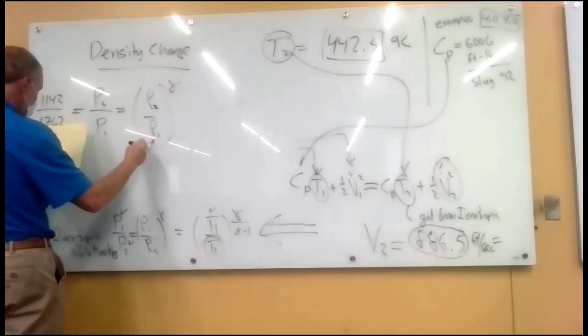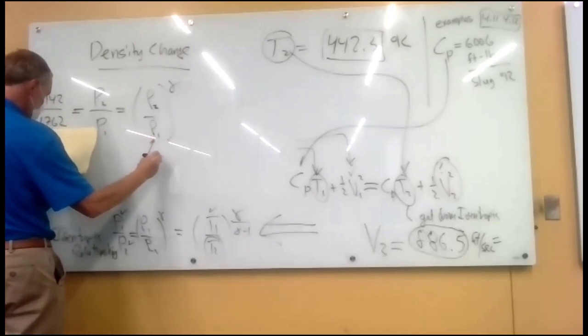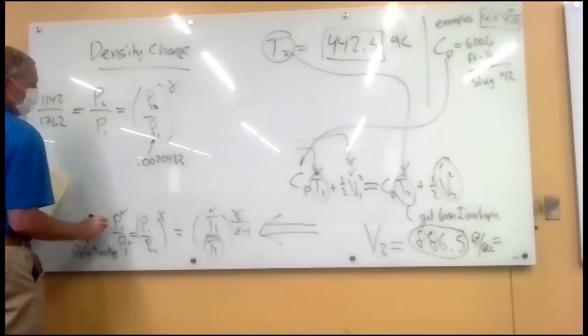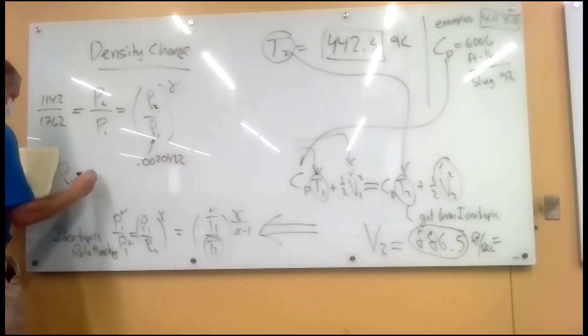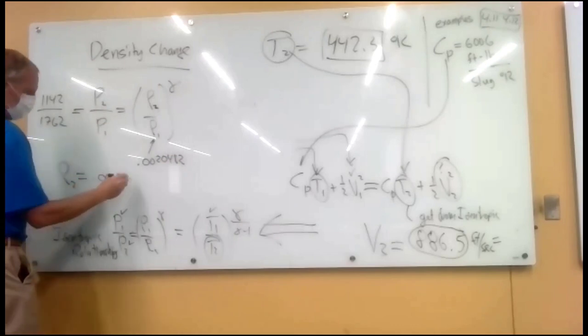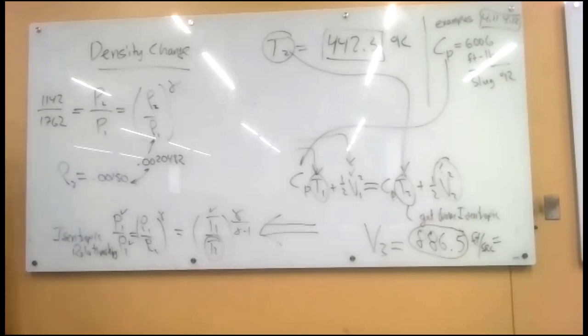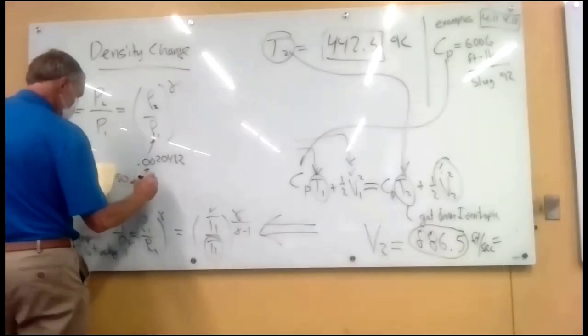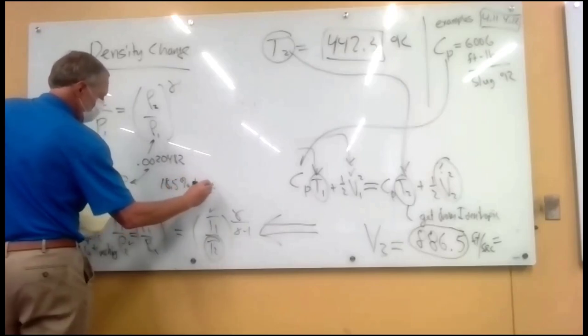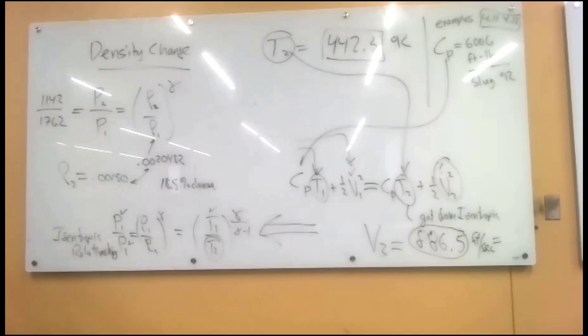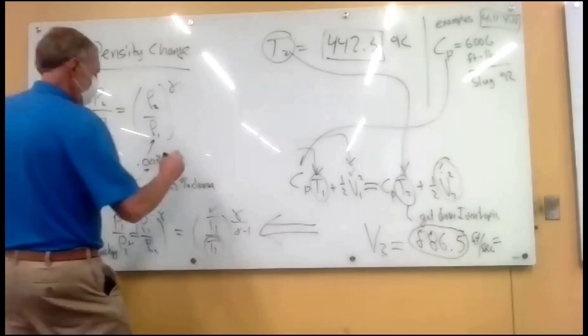And then the density rho 1 we knew from standard atmosphere. So if you punch the numbers on that, put in gamma as 1.4. Changes by about 50 out of 200. So this is about, I calculated this is an 18.5% change. And so that's significant. So that means assuming compressible flow, or not assuming incompressible, is totally valid. It validates